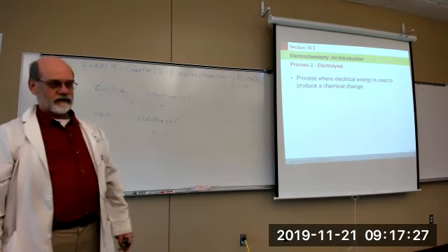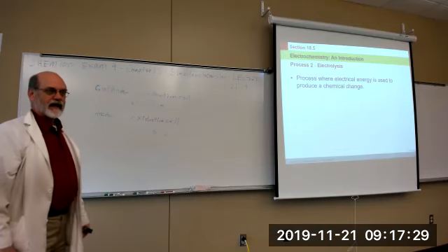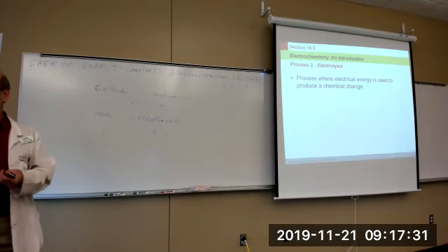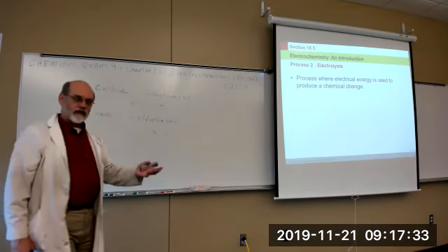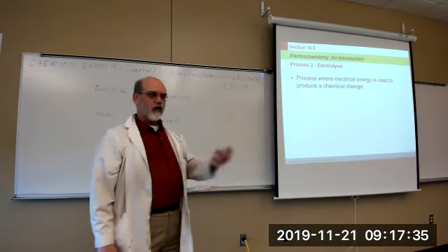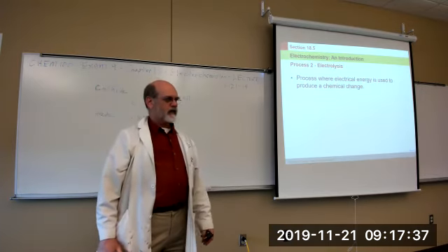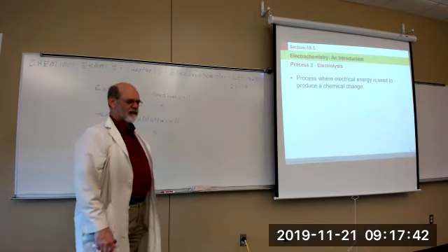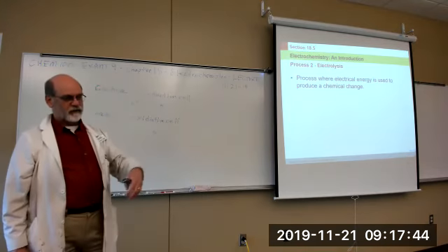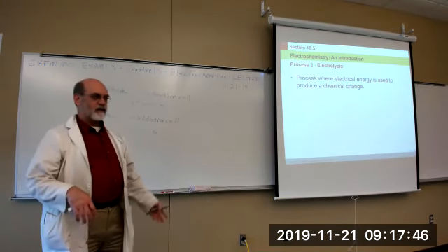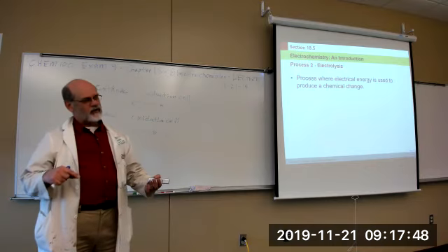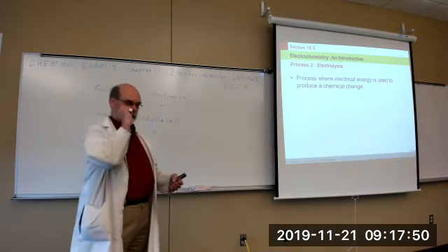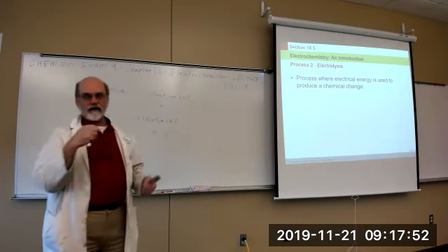That's electrolysis. And it's used in industry, used to be used in industry to chrome plate bumpers. You ever seen antique cars with chrome bumpers? Yeah, that's how they do it. They put that bumper in a vat with chromium in it, and they put a charge on it to run the reaction backwards and deposit metal on the bumper.